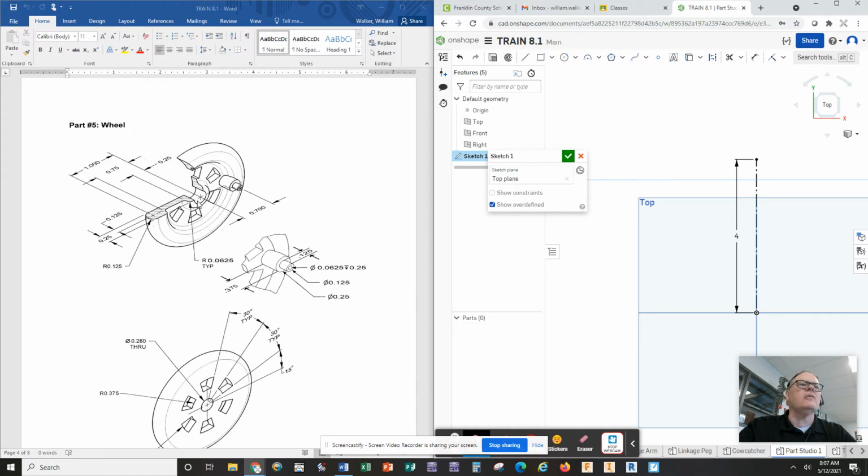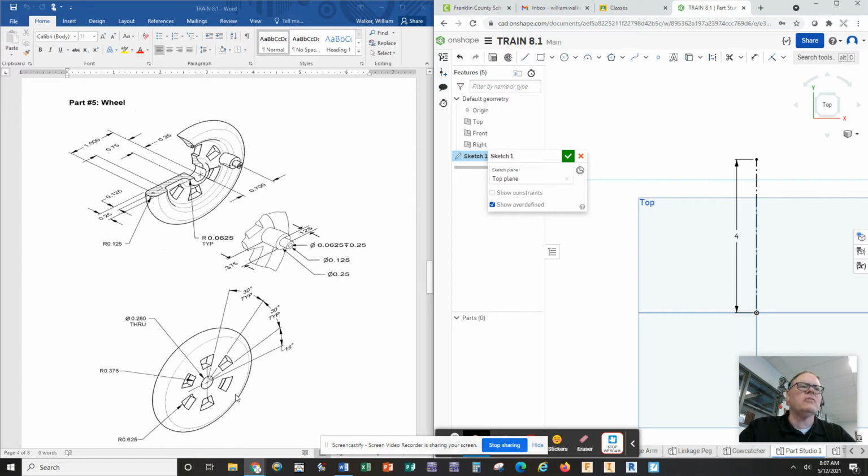Now you'll notice we don't really start drawing the cross section until a little gap here. Well, this little gap is actually this hole we see on the back picture of the wheel, and it has a diameter of 0.280. So if we're only going half the diameter here to move over, we're going over 0.140 before we start drawing. And if you put this little gap in there, when you revolve it, it'll actually give you the center hole of the wheel automatically.